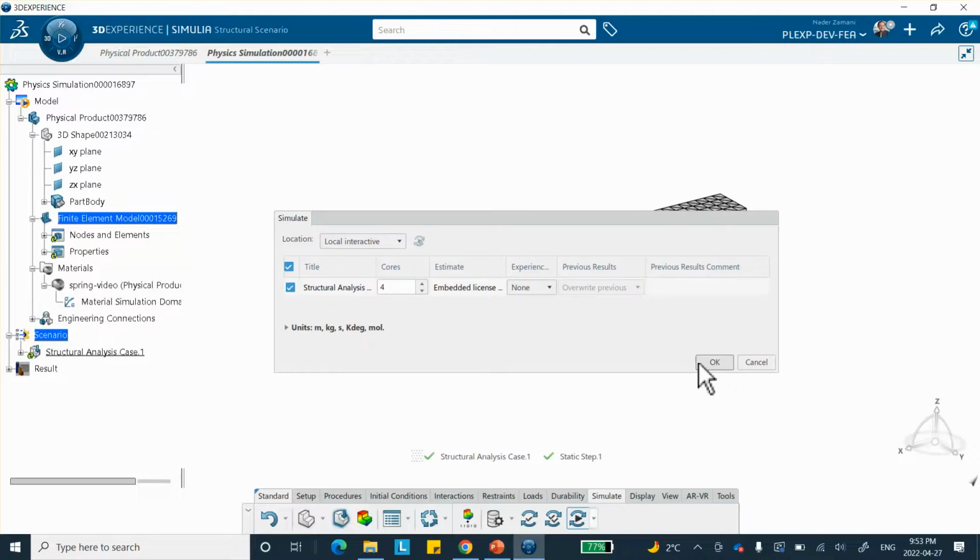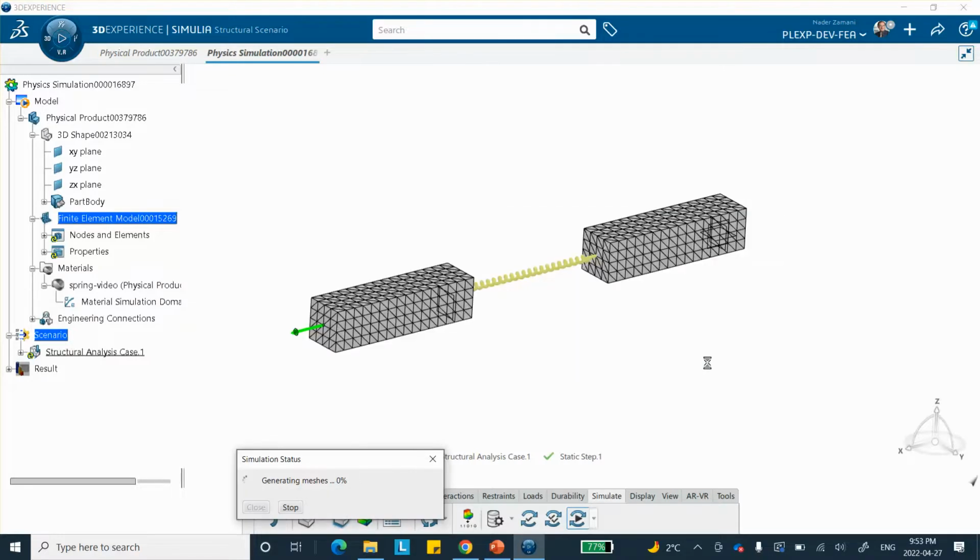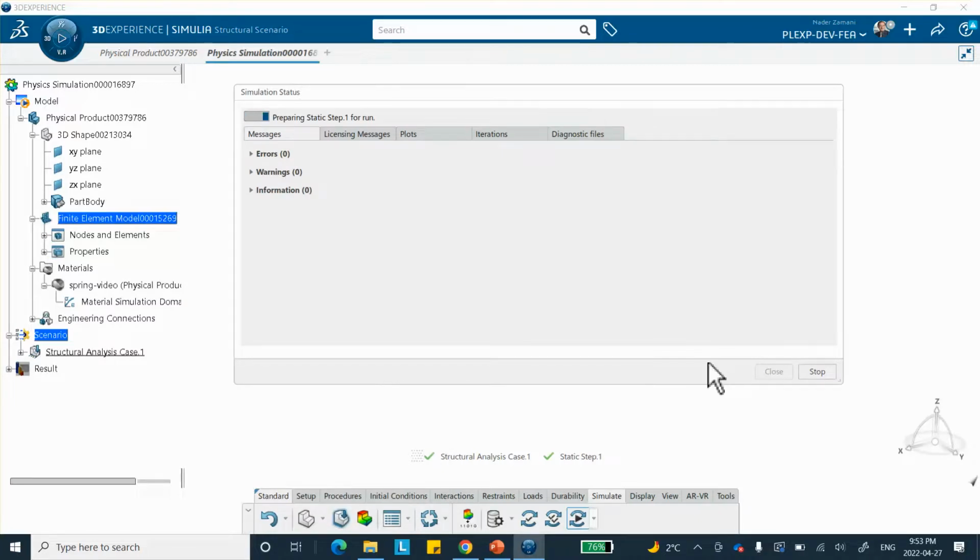Once this runs, I will come back and replace that one face-to-face spring with 4 vertex-to-vertex springs at the corners, and then of course you have to assign 1/4 of the stiffness to each of those end springs. You'll see that the deformation is going to be much larger than what it's supposed to be, but it's doable, although it's going to give you the wrong deflection.